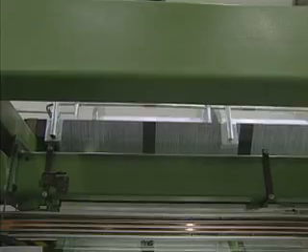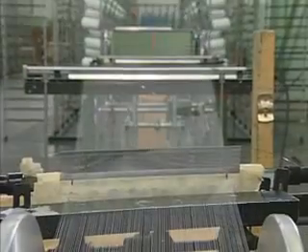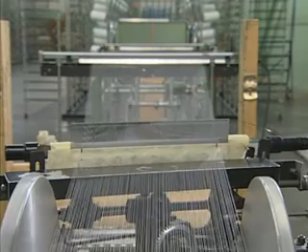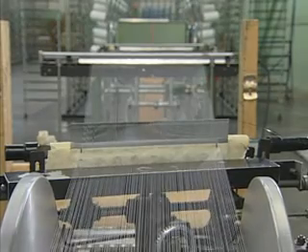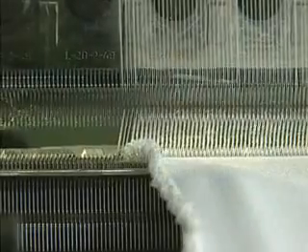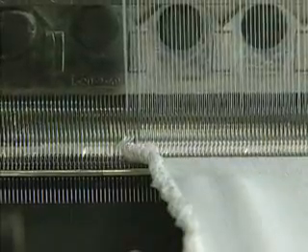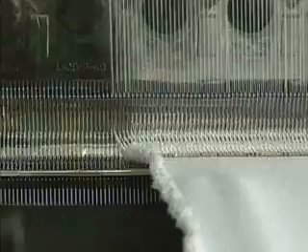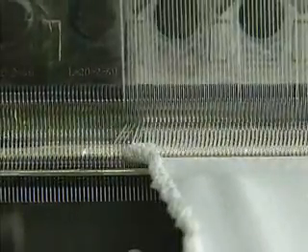The yarns are supplied to the knitting needles from a warp beam. The yarns are wound onto the beam from packages into a creel. The yarns arranged in this manner must be placed parallel to each other and under the same tension. Normally, for the most basic of warp-knitted fabrics, each yarn needs its own needle. For example, if 1,000 needles are used on this machine, there needs to be a minimum of 1,000 warp yarns.